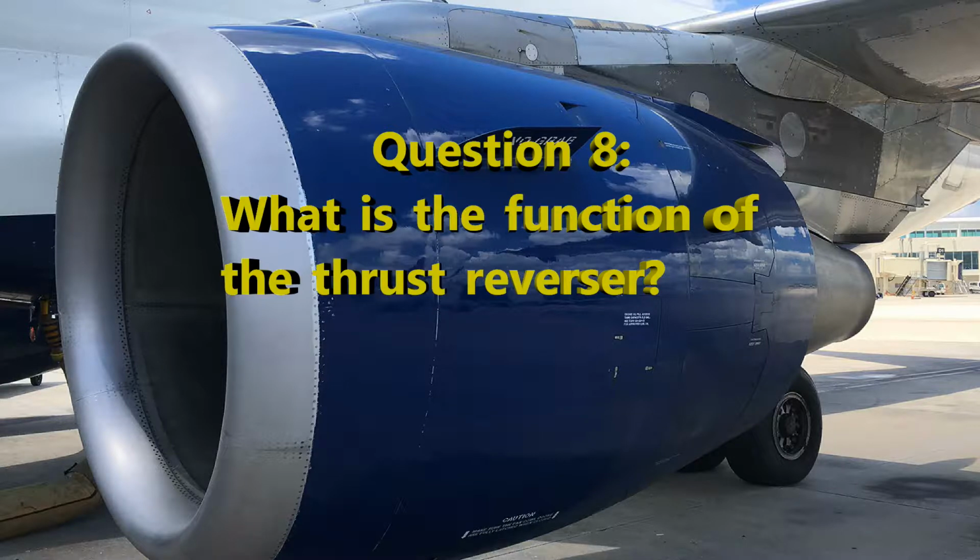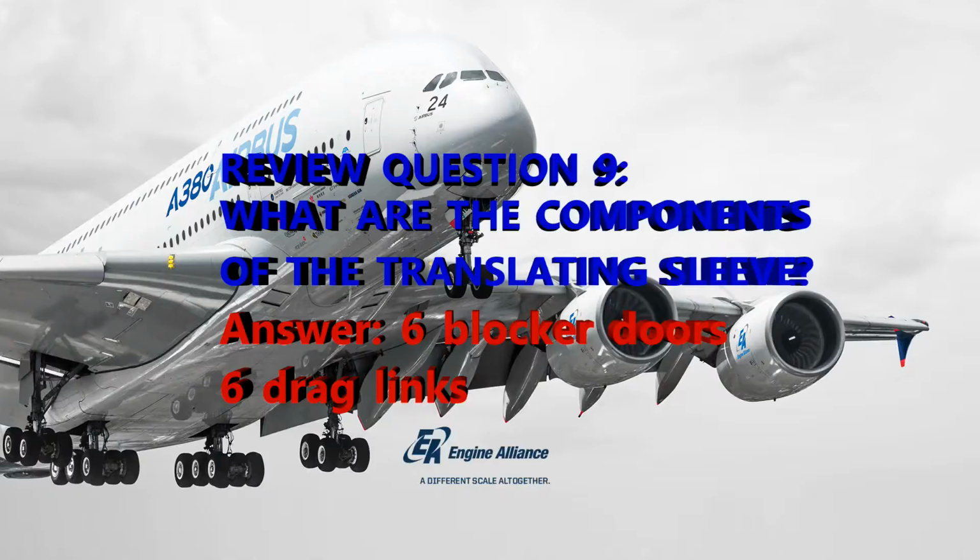All right, question number 9. What are the components of the translating sleeve? I didn't talk about links, but we do have links, and of course blocker doors. There's other terms you might hear in the industry, but for the purposes of this instruction, it's blocker doors. You have 1 sleeve and you have 6 blocker doors. For each of those you have 6 drag links. All right, so let's go back to our lesson.